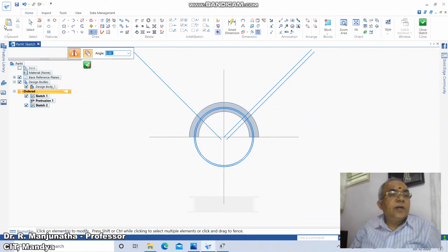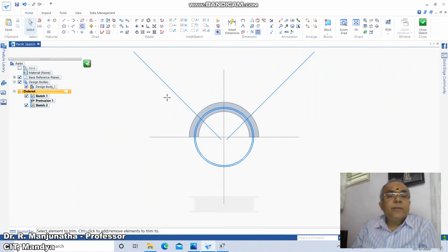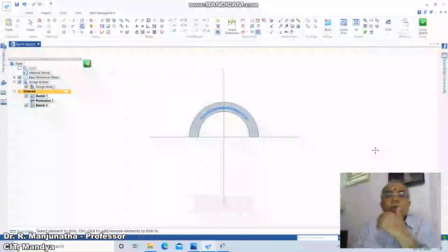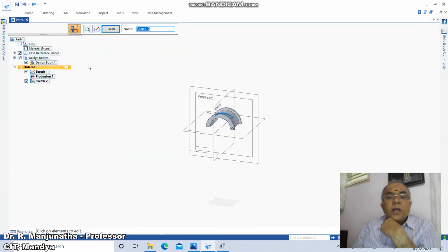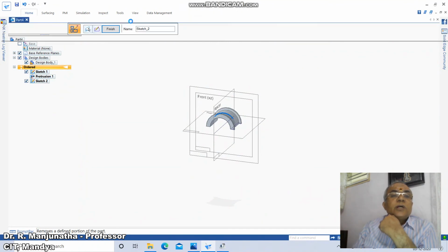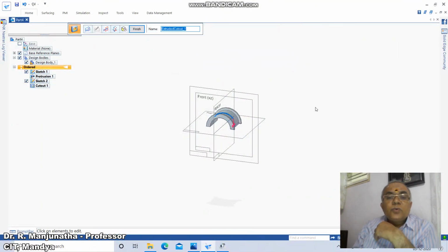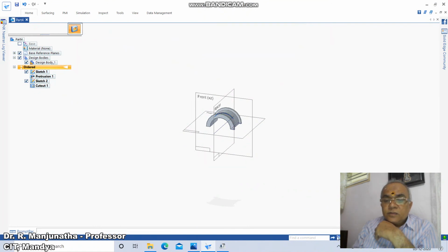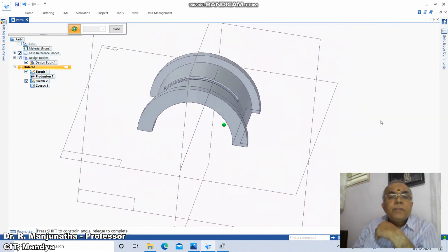Then go to select and select this and remove it. Then go to trim this side and this side and trim this side. Now we have the cross section. So now we need to go to close sketch. I need 3 mm depth, so go to cut, click on this, accept, go to symmetric extend and take the distance as 3 mm. So we got this groove which has been done by considering this dimension.